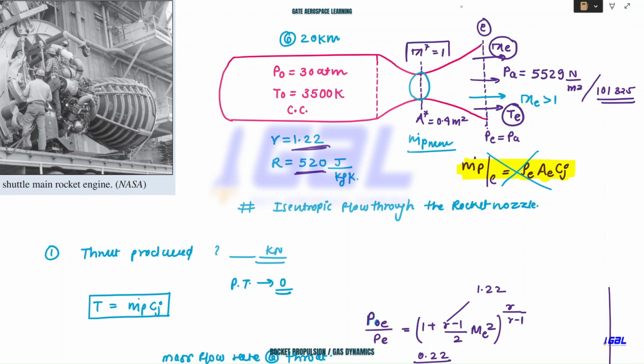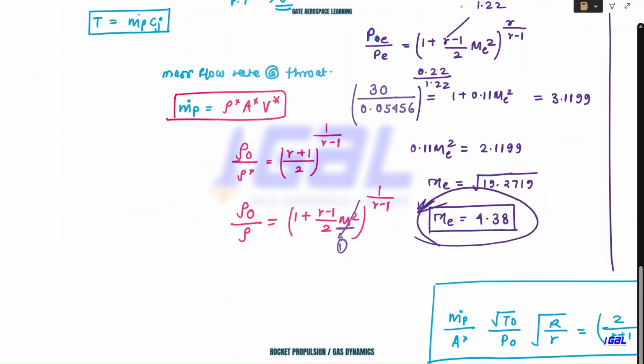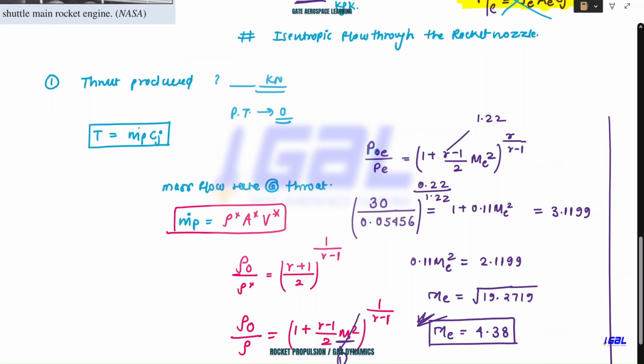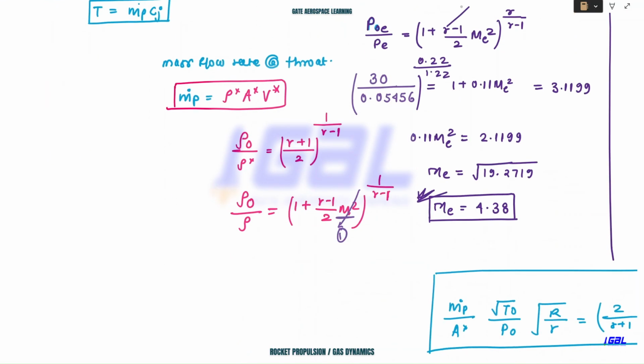Blindly you can say the Mach number at the throat for a supersonic Mach number at the exit, because my exit Mach number is supersonic, right? So your throat has to be choked always, right? So I can say M star will be 1. So I'll substitute M as 1 here, and the property which I will be getting will be rho star.